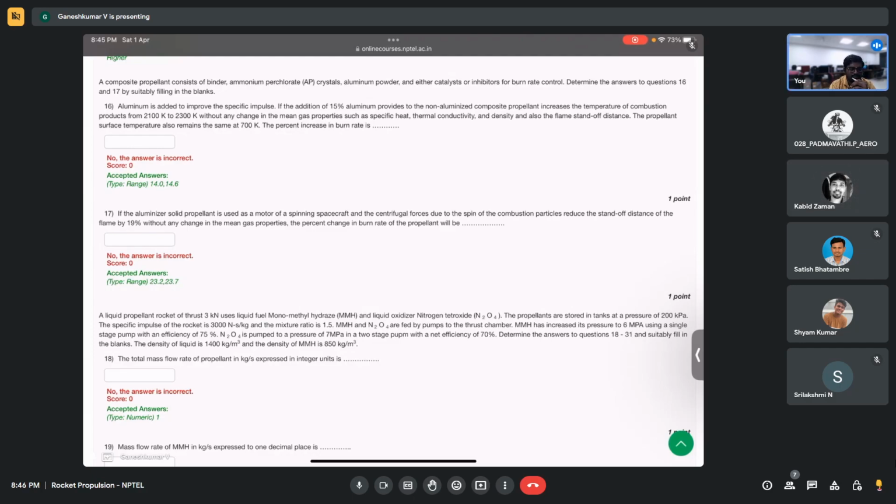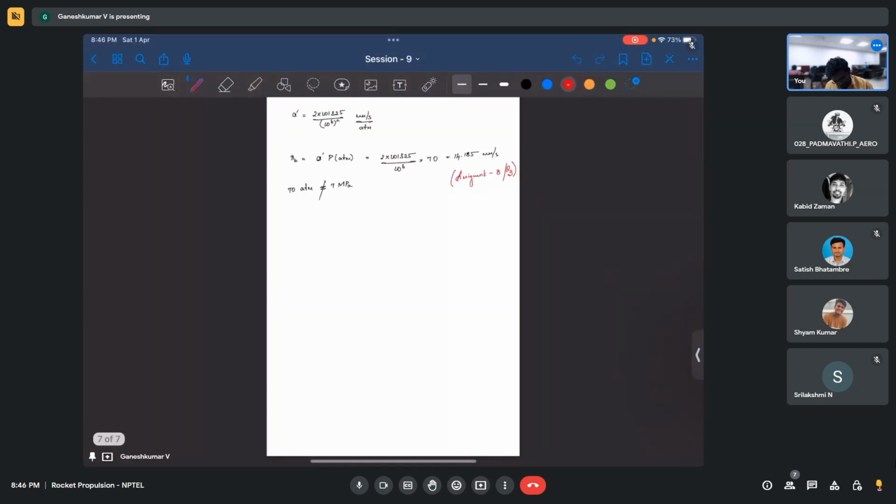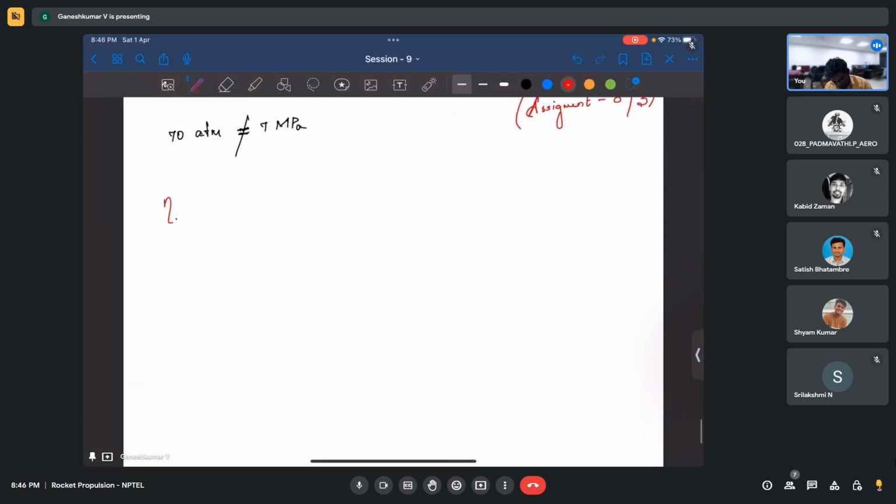Yeah, I'm not sure whether it is exactly into or not. The overall efficiency is going to be the total delta P Q dot divided by work given to the pump. So this work corresponds to both the stages, WP1 plus WP2.